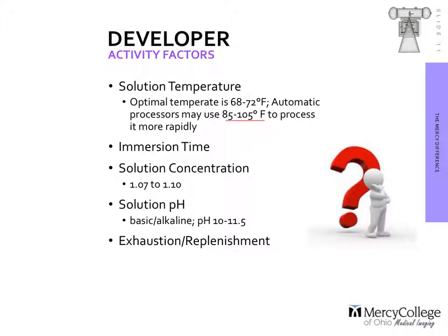Immersion time is another factor to consider though. The greater the length of time in the solution, the greater the optical density, or the more black it's going to be. So you have to be able to control how long it's immersed in the temperature. It's got to be a nice and controlled process that the temperature has to match the time, or we're going to have differing appearances in optical densities.